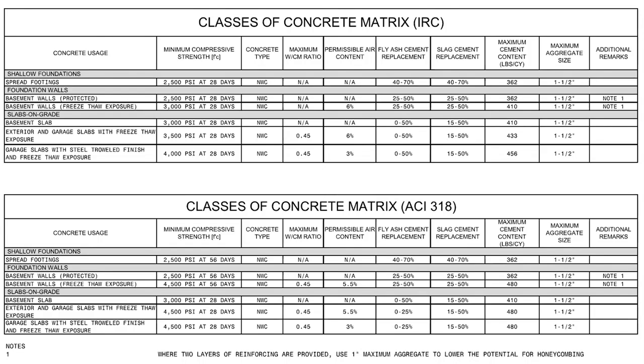We say not only what the strength of concrete is, but the strength of concrete at what time period. So you can see the bottom left, we have a lot of footings and foundations are at 56 days. That's our company standard. We have durability requirements such as the air content, and I think we've got, missing some other stuff here, but fly ash, slag. If we have sustainability goals, we might even show a maximum cement content, and then our maximum aggregate size.